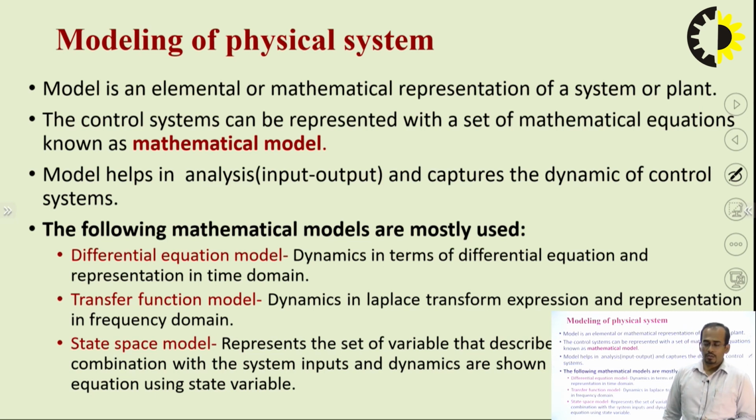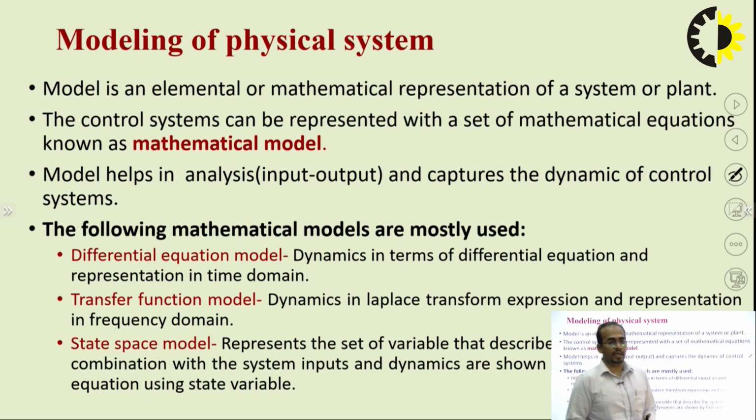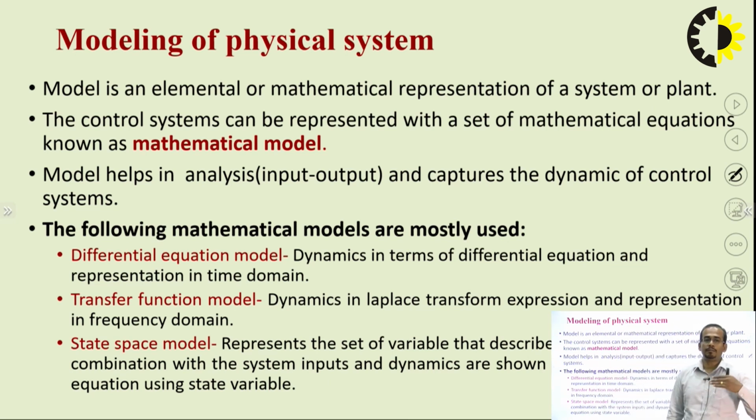Representation in Laplace transform is done in the frequency domain for finding the transfer function model, and dynamics in terms of differential equations are represented in the time domain. Whenever we represent the system in the time domain, we write it as a differential equation, and whenever we want to represent the system in the frequency domain, we write it using the Laplace transform. We are finding the Laplace transform of the system.